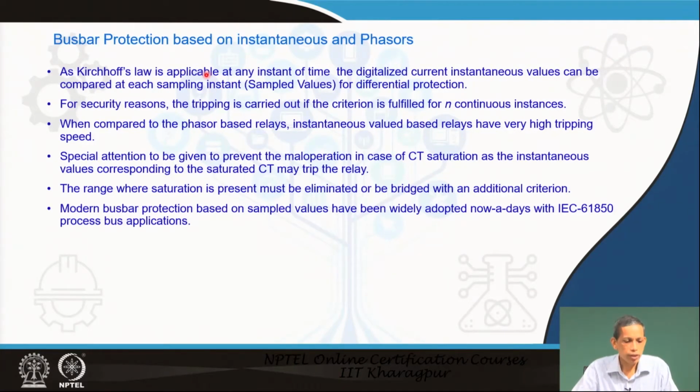Again, in the same low impedance protection perspective, we categorize into two: one is the instantaneous approach and the other is the phasor approach. Earlier we learned for line protection and transformer protection how phasors can be applied. Because the bus bar is a very critical element in the system from a stability perspective, the protection should be as fast as possible. So relays also use the instantaneous or sample based approach for the protection using the differential principle.